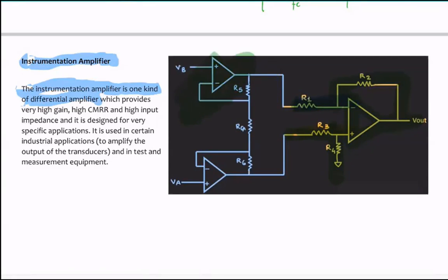What do you see in the blue lines over here? What kind of circuit are these? What kind of op-amps are these? We just learned about this also today. So anytime you see a circuit and you see that the output is directly connected to the negative terminal, you consider it as a voltage follower or a buffer, which has a unity gain.